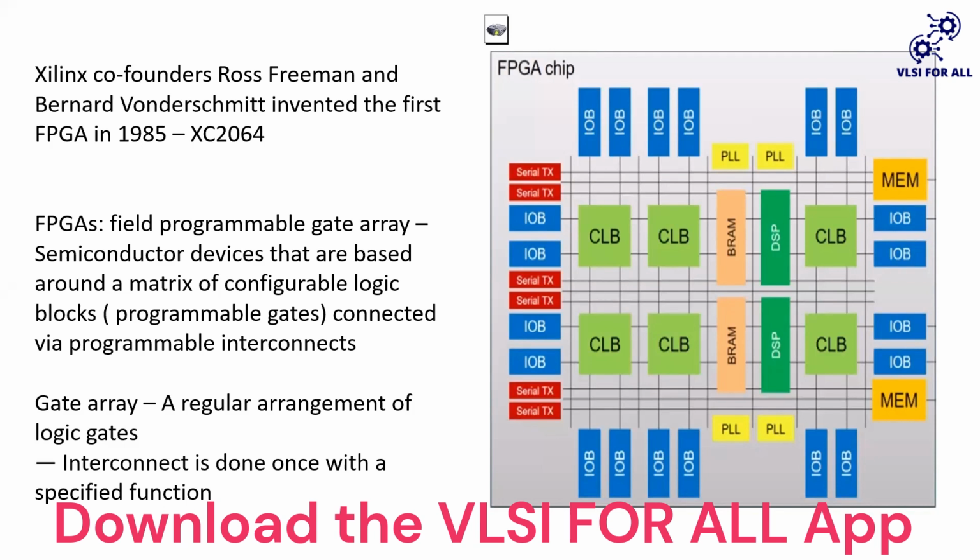Yeah, CLBs are configurable logic blocks. These are also logic blocks, basically, that we already find in FPGA kits like Xilinx Virtex. Whatever board we are taking, these are already defined in those boards. How will we map? There is a tool that will generate the mapping file.